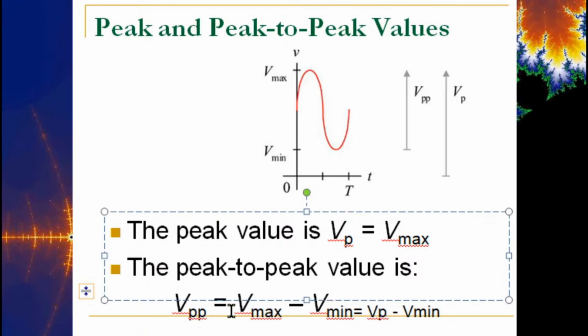Because the maximum is always going to be the peak. So like here, even though they're riding on the DC signal, the peak is always from the 0 axis, and so it would be V max. So in your equation for your sine wave, it's going to be this peak voltage. Even though the peak to peak might only be, let's say, 6 volts, this could be 9 volts up here, and 9 volts is what you use because that's the maximum possible that you could find with this.